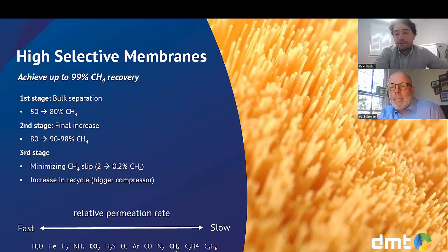What's interesting is the permeate is a pretty low pressure. It's almost ambient. It really depends on what pressure it's tied into on the other side, whether it's going out to the stack or being tied in as a recycle. But usually it's down to almost 10 to 15 psi coming out of the permeate. That's really fascinating. So if you're going onto the membrane at 200 psi, going through the membrane, you maybe only have 10 psi left. So that 190 psi is all that energy it took to get through the membrane. That's correct. Yes.